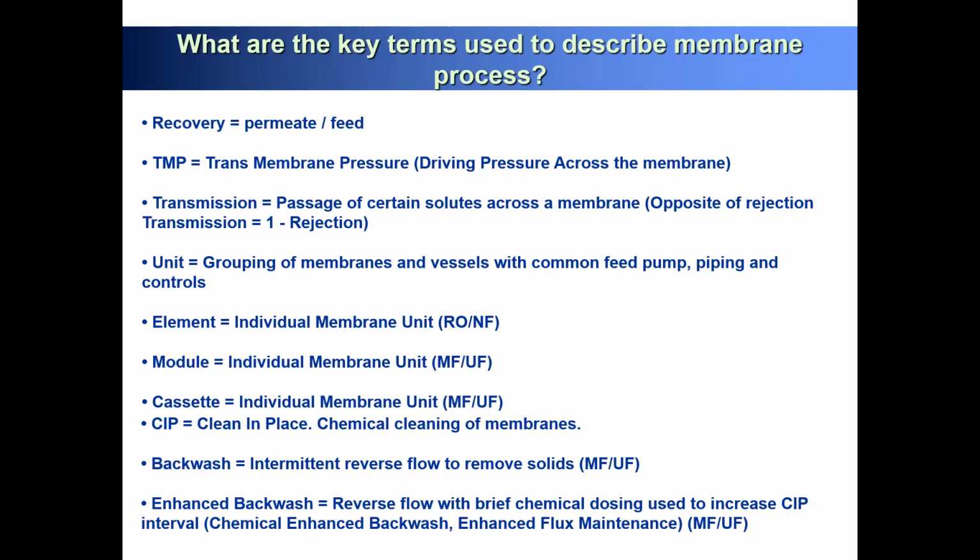Then fouling accumulates on your surface, and the flux keeps decreasing, and the transmembrane pressure keeps increasing. So in this case, you backwash, then detach the fouling from the fiber, then you just waste your backwash water and start again with your feed water, and you have a better water flux. So that's the backwashing. So backwashing is for your precision ultrafiltration and microfiltration, where the large pore size can be applied.